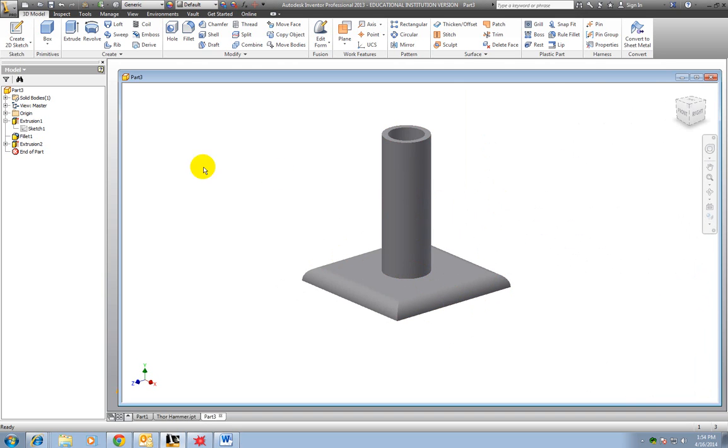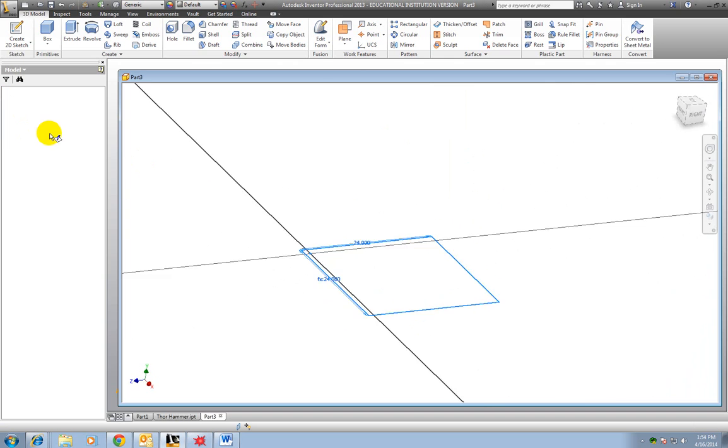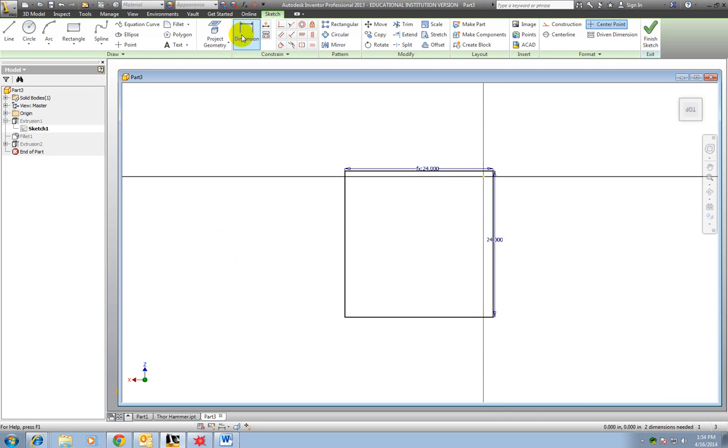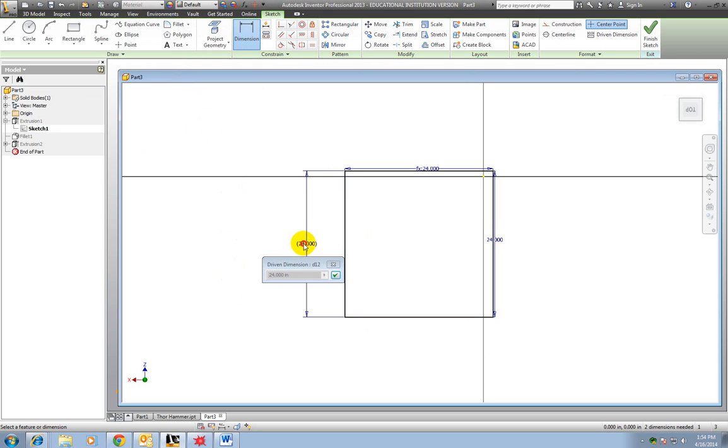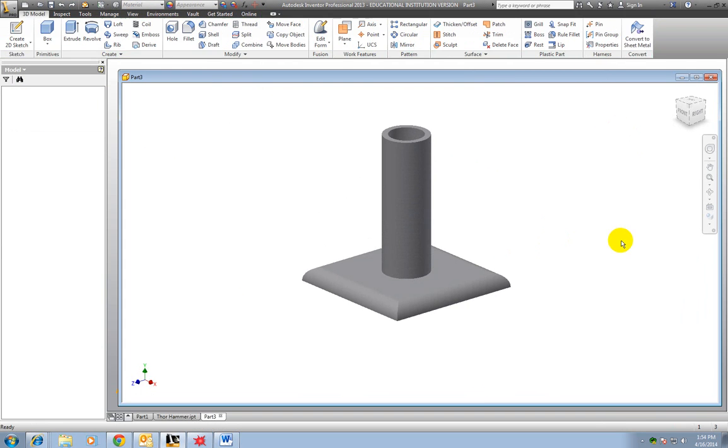You just go in, and if I look at this, I can tell what dimension something is. When I do this, it tells me that dimension would be D12, so I can go back in and look. But obviously, I want to get rid of that because I don't want things to change when my parametric equation is done. So I'm going to click Edit that sketch.